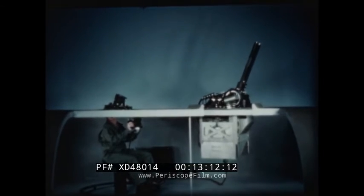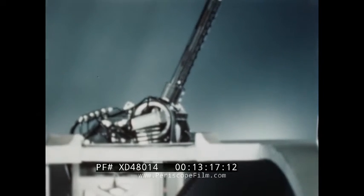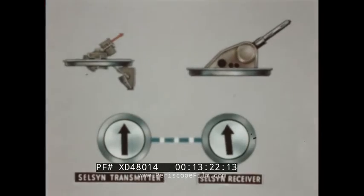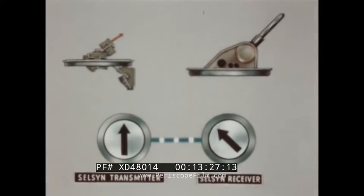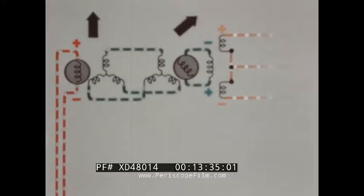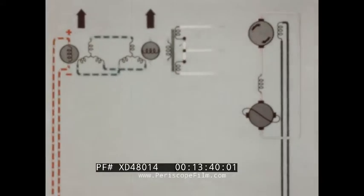With the system as developed so far, the turret will follow the sighting station, but the action is not smooth. When the sight stops, the guns will not come to rest. This hunting motion is caused by a tendency of the turret to over-travel. Hence, the guns and receiver are driven back and forth across the position of alignment. This causes a reversing voltage to be applied to the turret.